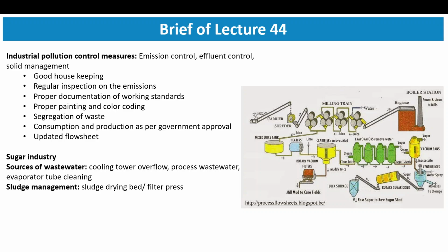If you mix both, the concentration will change, but the amount of water you need to treat will be 50 liters for each process. Otherwise, the volume treated would be 20 and 30 liters. So segregation helps in minimizing the amount of water treated.